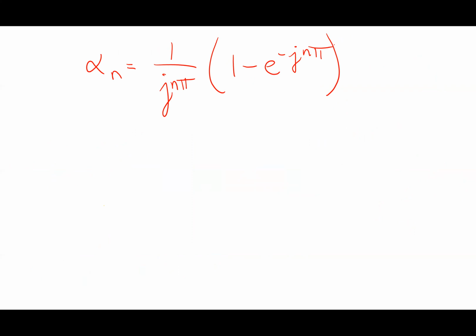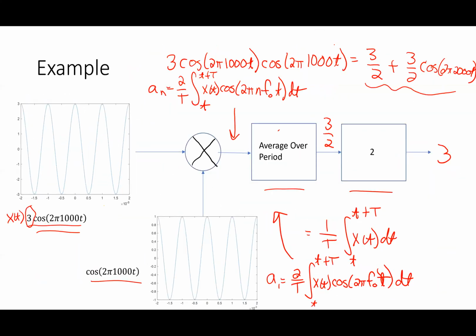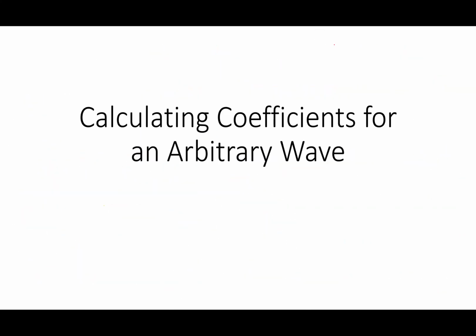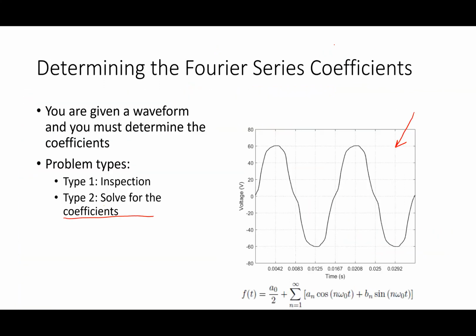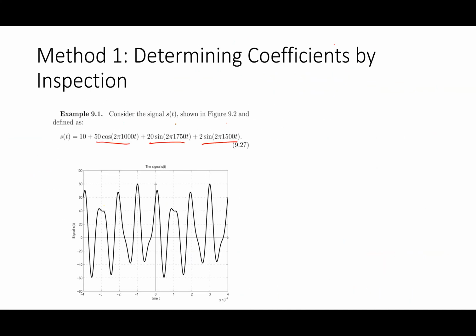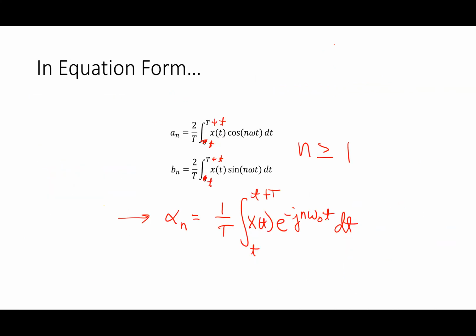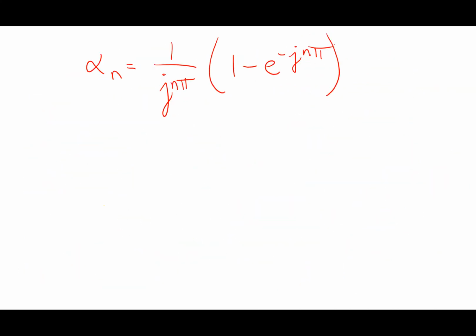One of the things that I said when I did the square wave at the very beginning, I showed you the picture here, right? I said that only the odd harmonics were there. Now, this is looking at sines, but if I'm doing it with the complex version of the series, it better be the case that there are no even harmonics present here.